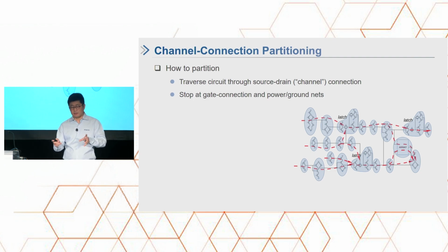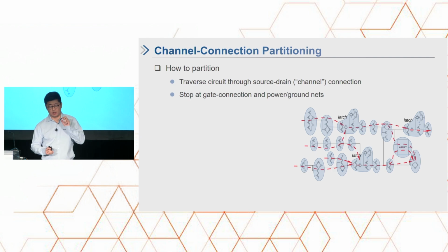graph that's a little bit like a standard cell design. So we partition the bigger cell into smaller standard cells, but this is done automatically, and we can analyze the logic of each cell automatically and generate the stimuli to simulate each small block, small partition.